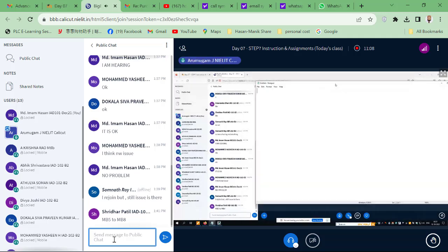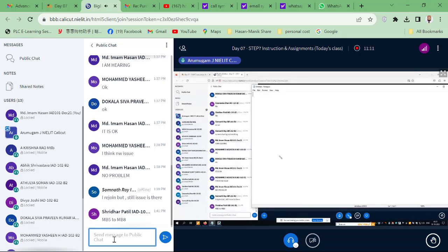In our case, the first step is the project. For example, this is your RTU, and we are using a Siemens controller for this RTU. From this RTU, we connect to the field instruments, which collect the data or control the plant. Then there is communication using a communication protocol, such as Ethernet, Profibus or Modbus, and then it is connected to your MTU system.